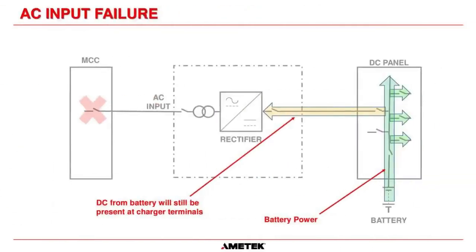Okay. Now, if you have a power failure at your MCC, the 480 volts disappears. And a lot of people say, well, okay, at that point there, we switch to battery. We never ever switch to battery. There's no switching mechanism that happens. My analogy usually is it's just like a laptop. When you've got your laptop plugged into the AC outlet, everything works fine. And if you pull that AC outlet out, nothing switches. The battery is just there in parallel.